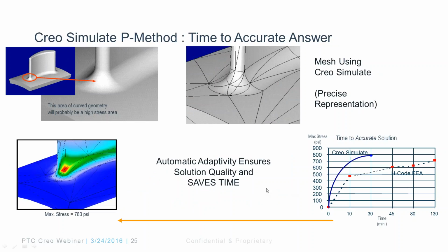I'll show you with an example on this accuracy thing because it's very important, even if you're currently using Creo Simulate, to make sure you plot those P loops or the P graphs for stresses or deflection, strain energy, so you know that your solution is accurate and you can start making some engineering decisions based on that solution, or maybe make some improvements based on that report that you got from Creo Simulate.